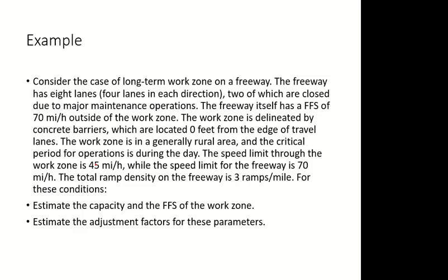Same thing with the weather. If most of the time the weather is good, a few days of rain will not require the adjustment factors and the new speed and capacity and so on. Adjustment factors are only done when the condition is long term. The condition is persistent, it is frequent, it happens most of the times of the year.